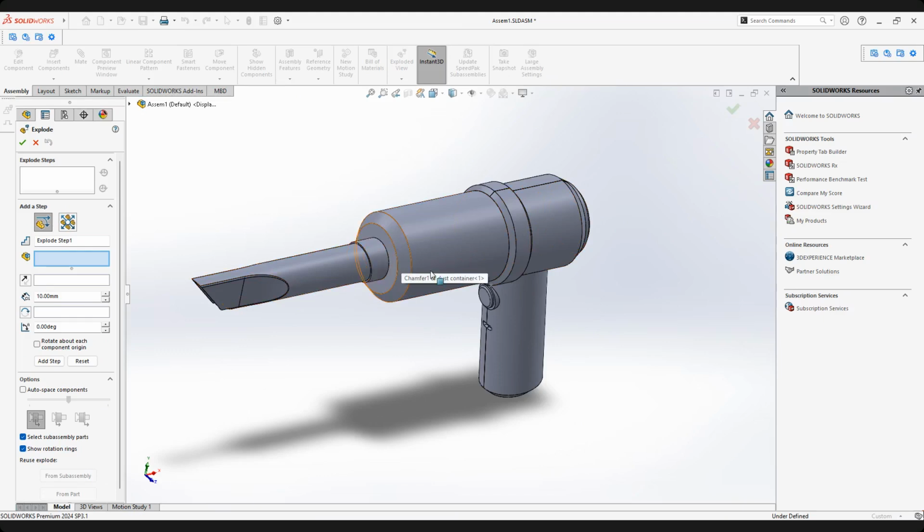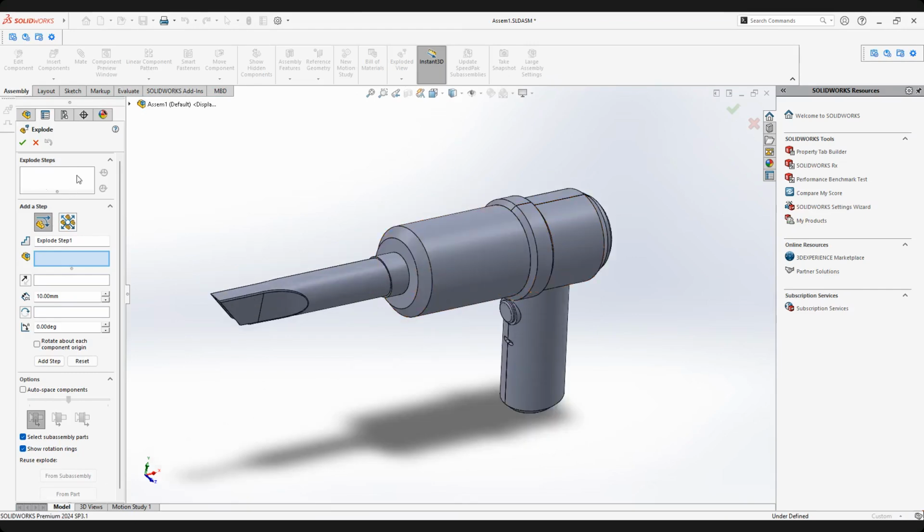So how do the internal components work, how does the flow go, how do we place the battery, how is the cap attached to the other part, because you are in full assembly mode. You just show all the parts in position, but you cannot explain how the parts relate to each other. So that's why you have to make an exploded view. Okay, exploded view, I already clicked on that one. So here, whatever part I move will be recorded as an explode step.